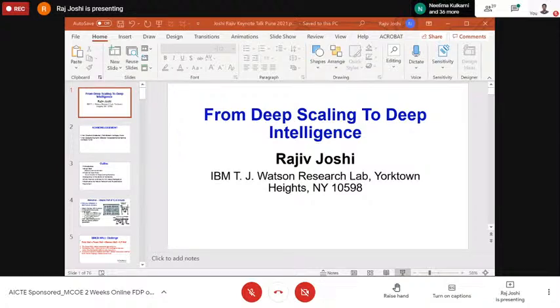So what is this challenge, the memory wall challenge? Basically, data movement between core and memory is dominant in big data applications. So the memory wall is equal to the power wall plus bandwidth. And the bandwidth is a technology limitation, non-scalable. If you plot the bandwidth and the evolution of the application, you see the system requirements are increasing. However, the memory systems offered are almost saturating. I mean, we need innovations here, right?